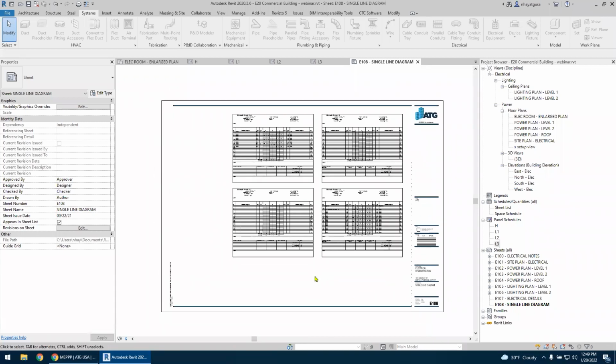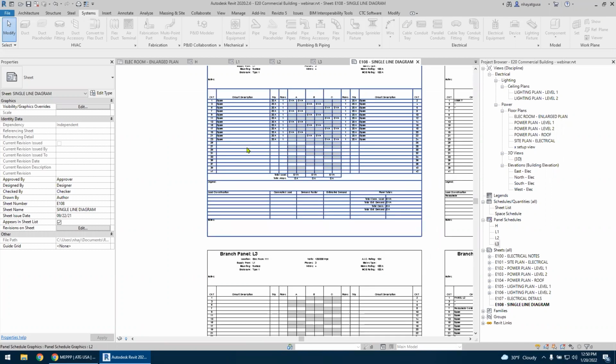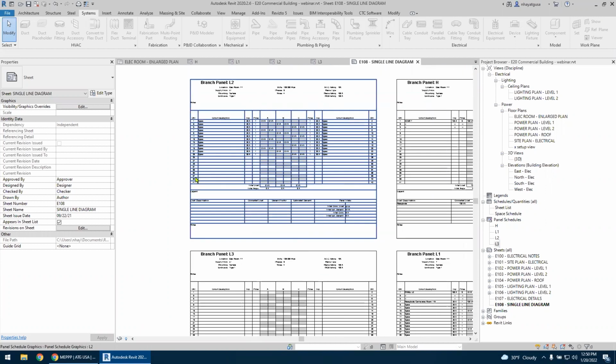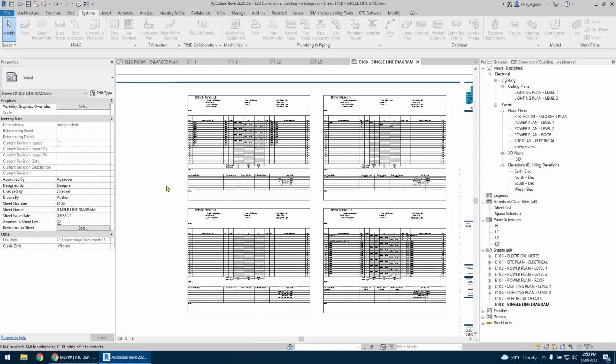And this is me moving fast, knowing what I'm doing, not having anything here, and it's still taken me almost an hour to get to this point. So now you can see Revit out of the box. If you've got a template set up already, or if you've got that productivity pack, this should move a bit faster. You won't have bugs like this with empty ones that don't match. It'll automatically shrink it to 24. Your receptacles, if you got the productivity pack, or you've got someone who's developed some non-hosted ones, they don't have to be stuck on walls. Your lighting, your circuit tags are probably fixed already, but out of the box, you've got to fix all that stuff on your own.